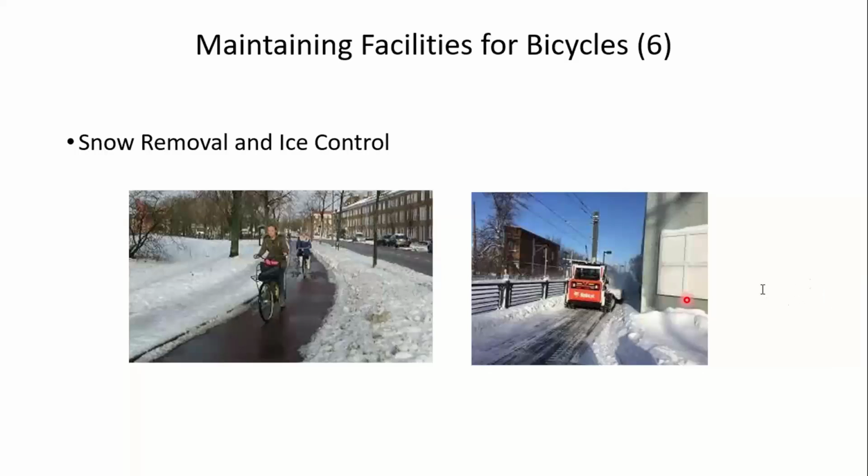And then Nicholas asks, during an alteration project, do adjacent sidewalks that are non-accessible need to be upgraded? For example, fixing trip hazards from upheaved sidewalks. Great question, Nicholas. And thanks for asking that. That's a question that comes up probably every time I talk about ADA and the Kinney versus Jerusalem case. And the short answer is no, you don't.